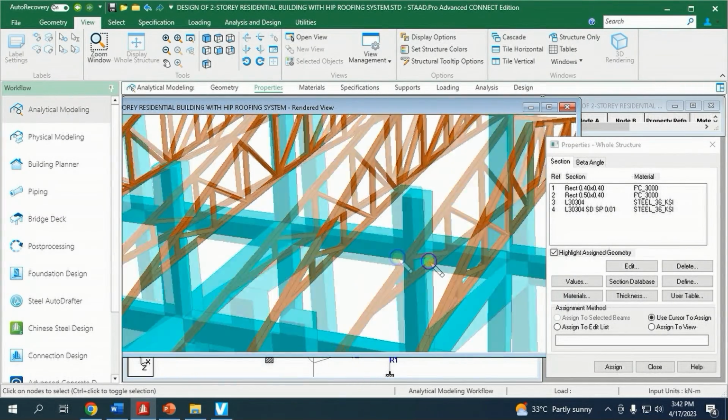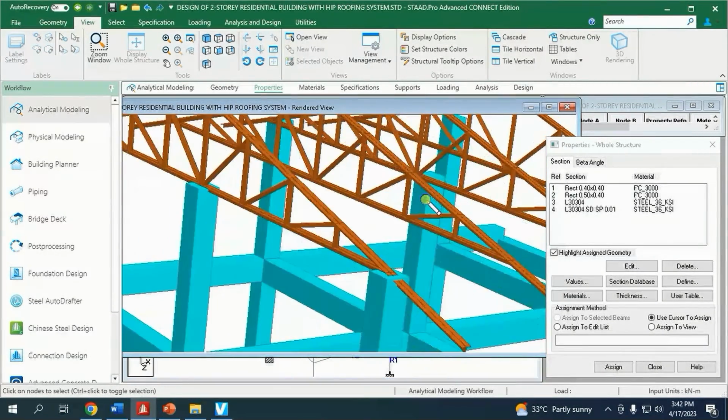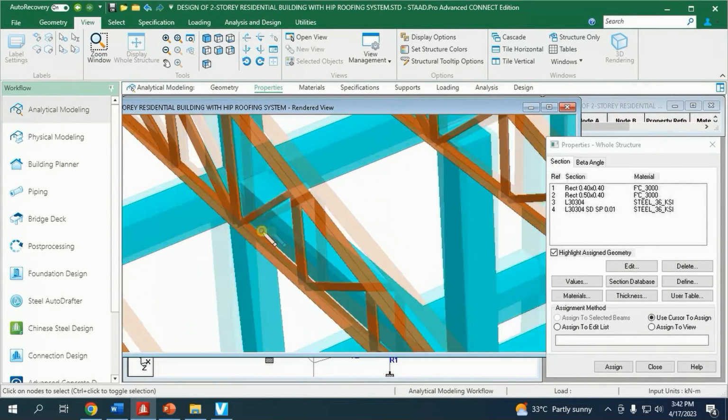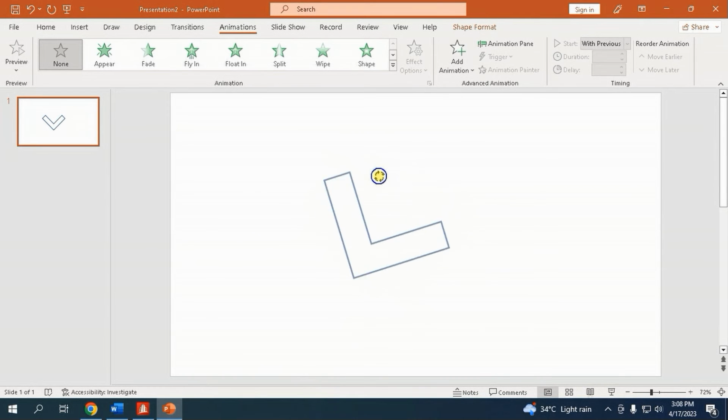And also the web member is not in the correct orientation. If we look at the web member in the top view, it is positioned like this, and the angle with respect to the horizontal line is 45 degrees. Normally, it should be this way. So we need to rotate it by an angle of 45 degrees.